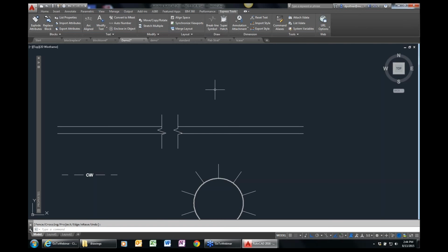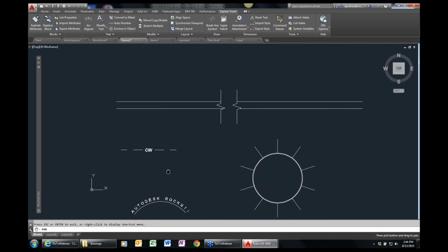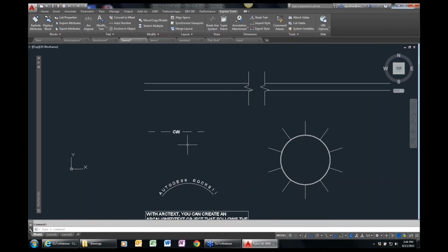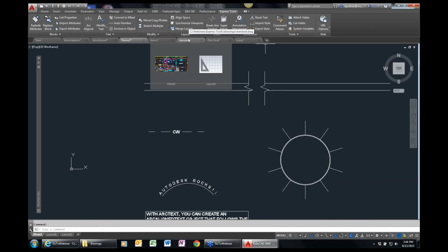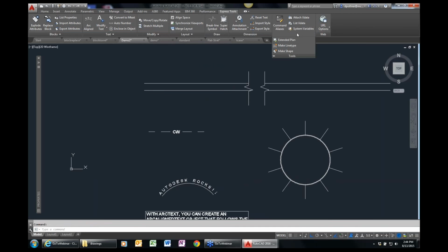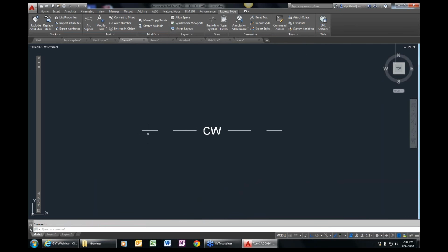Have you ever had a line type that you want to create but don't want to define it in the LIN file? We have a tool called Make Line Type. So pretty simple. In this case, I've drawn a couple of lines, one a little bit shorter than the other, and I put a piece of text in the middle and kind of repeated it on the other side.